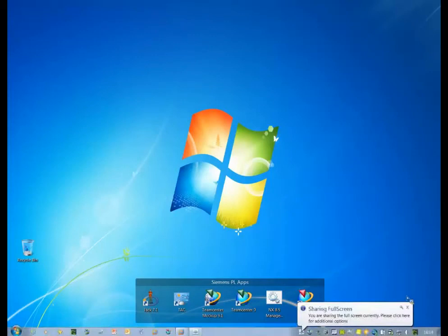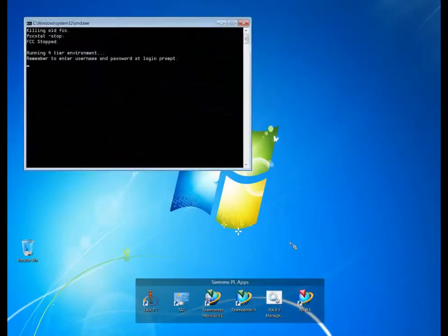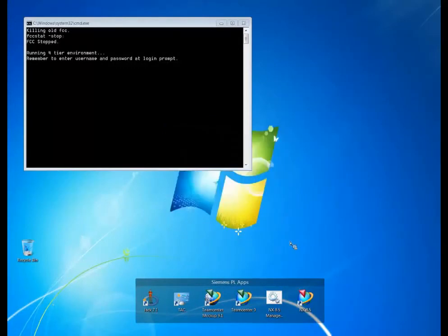Okay, so hopefully everyone can see my desktop. I'm going to start NX in manage mode. What you'll see is it's just a double click on the icon. NX starts, but because I'm in manage mode, I have to enter some user credentials. So all the open and close and the file interaction is going to be between the PLM environment and NX. There isn't any information that's coming from the operating system. So I enter my username and password, and give the system a few seconds to launch NX in manage mode.